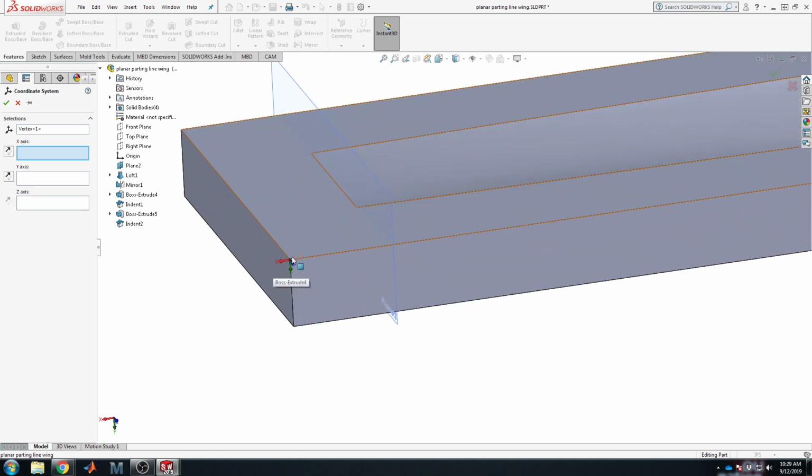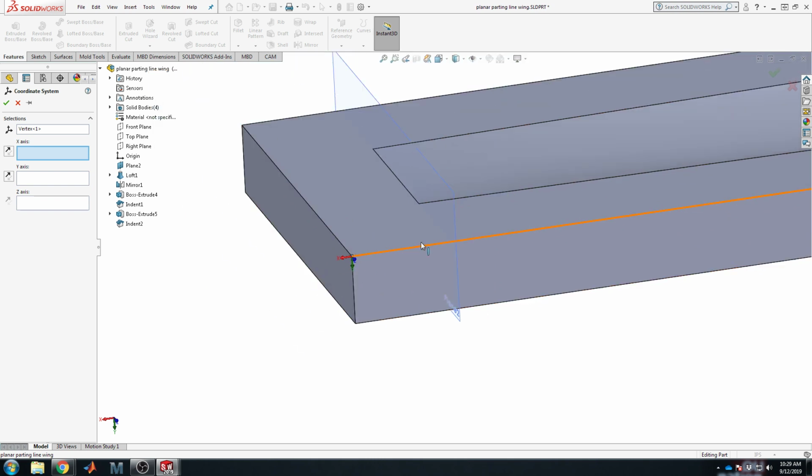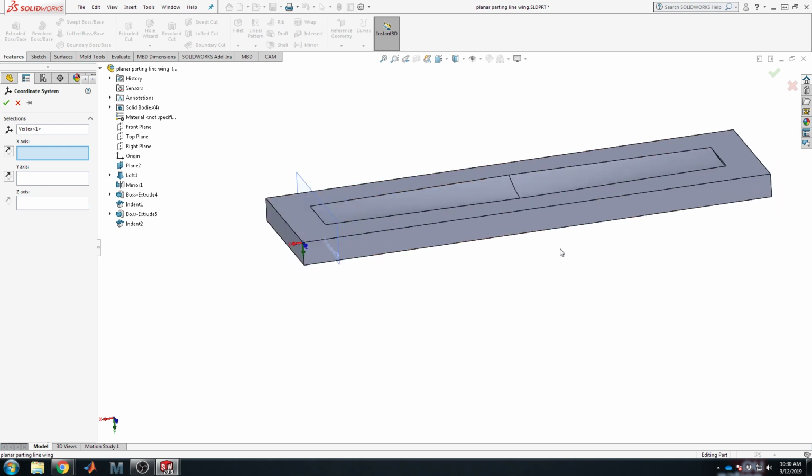Top of the material, so that way whenever you touch off, you can touch off on the material block before you cut it. You can set it towards the top. With molds, basically everything is referenced to this top surface you're going to be cutting. So if you wanted to push that 0 down into the material, maybe 1/4 of an inch, 1/8 of an inch, to take off any sort of surface imperfections. Maybe the mold blank got dinged in shipping. You want to make sure you have a nice flat parting surface.